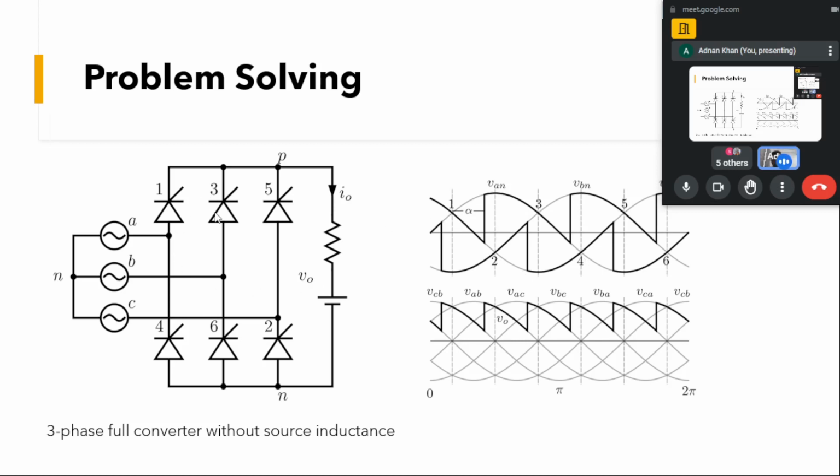Had there been diodes, they would have started at 1. For the top 3, whichever of the SCRs or diodes is at the higher anode potential will start conducting. Now we turn on these devices at a certain alpha, which is measured from the natural commutation point where the device would otherwise turn on.